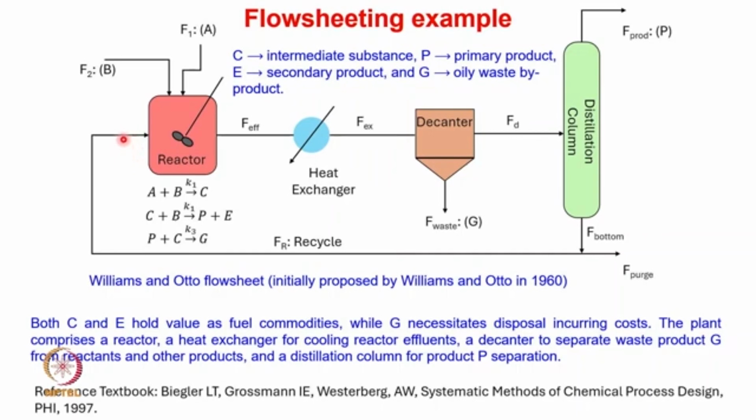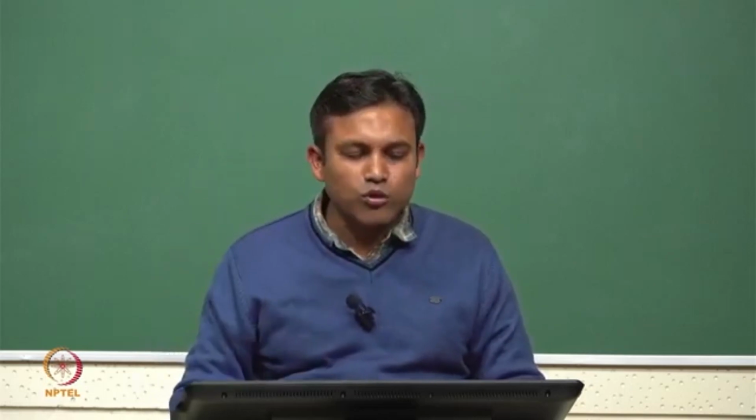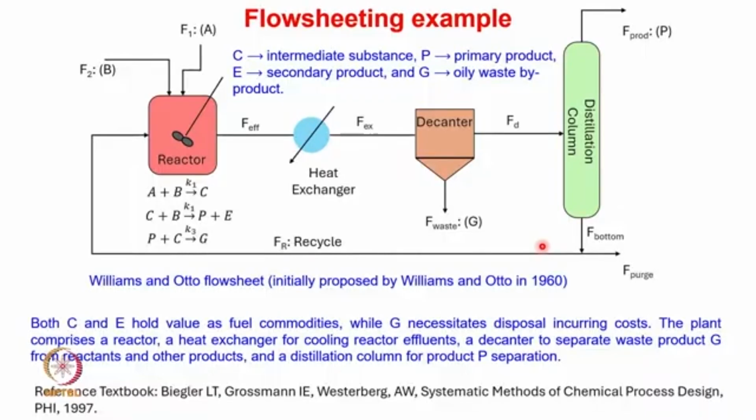That fraction we assume initially. Based on that we are sequentially solving all these five units, and then finally we again calculate the concentration of different components present in the recycle stream. If these are not matching, we have to do this simulation repeatedly in an iterative manner till we match all these calculations. So that is what is done in the modular approach.